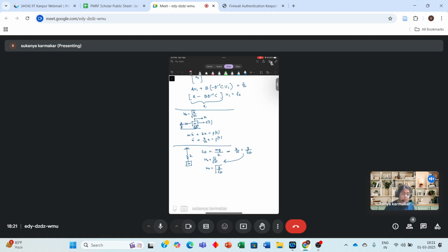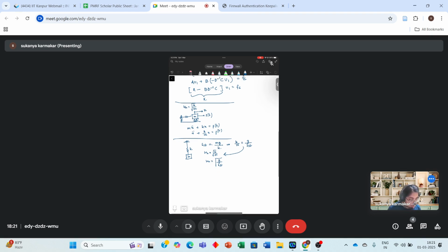So what was the doubt majorly? Like how it is derived? Okay, so omega n I could write like this. Is this fine? Then the time period is 2 pi by omega n, so just substitute it here: 2 pi times the square root of delta static by g.